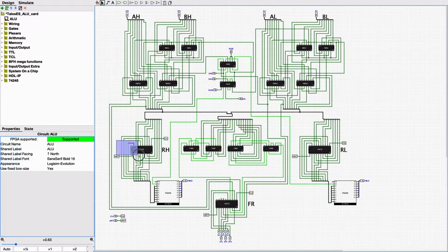Now these are the result registers, result high and result low. They are also connected to clock and an active low reset, and the clock and the active low reset come from the backplane connector. I'm using this notation here with these tunnels, not to draw more wires going everywhere, so when a signal has a large fan out, I just use a tunnel notation to simplify the diagram.